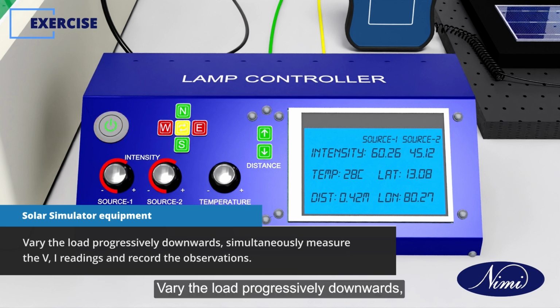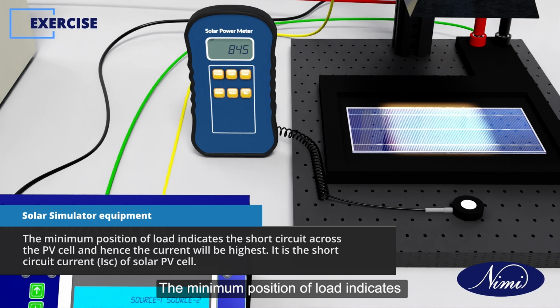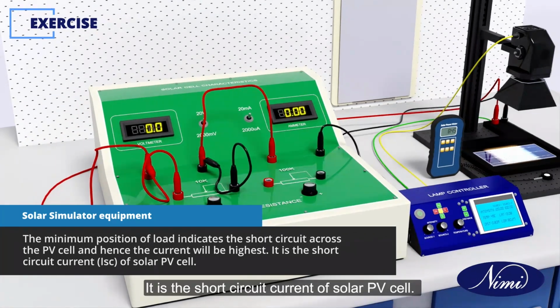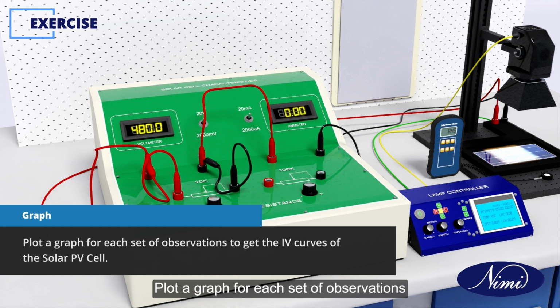Vary the load progressively downwards. Simultaneously measure the VI readings and record the observations. The minimum position of load indicates the short circuit across the PV cell and hence the current will be highest. It is the short circuit current of the solar PV cell. Repeat the above with reduced intensity at different levels. Plot a graph for each set of observations to get the IV curves of the solar PV cell.